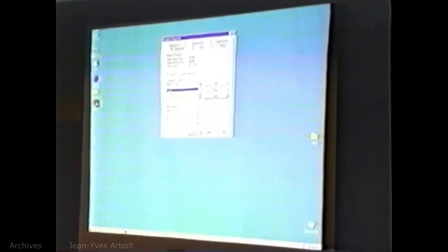Just some of the things that are common in all these display properties is you want to have the overlay planes turned on. That'll do the hardware overlay planes. Otherwise, things like your timeline or your Artisan are going to be really slow because it's going to have to do overlay planes in software. You don't want to do that. So it's going to look like hell. You want to have the 4-bit overlay planes or whatever number of overlay planes turned on. You want to have minimized pairing, is what they have right here.